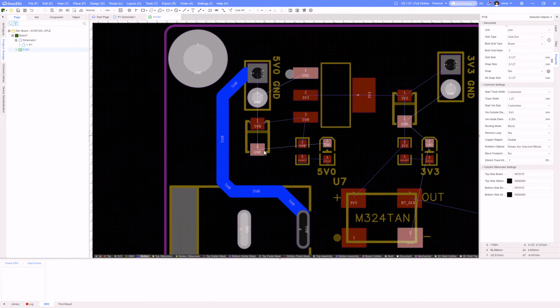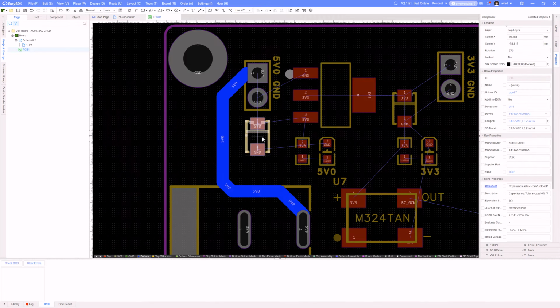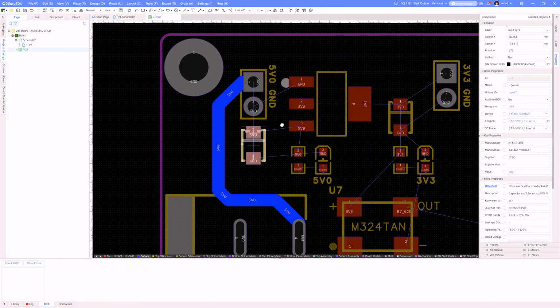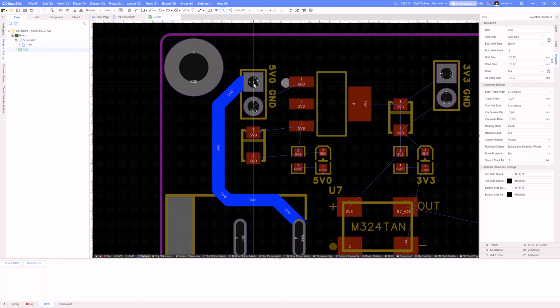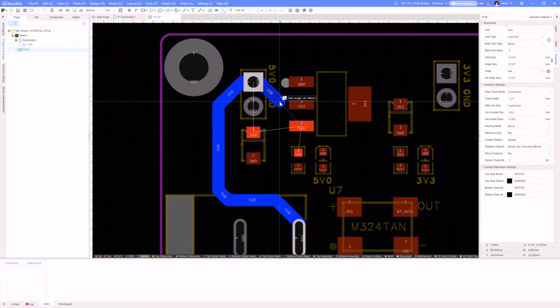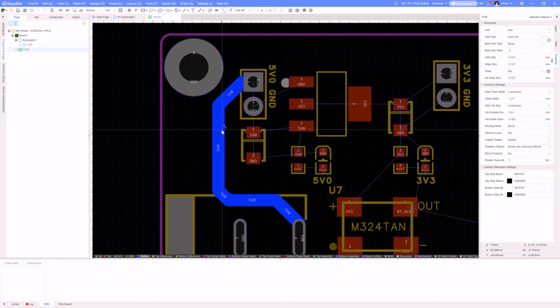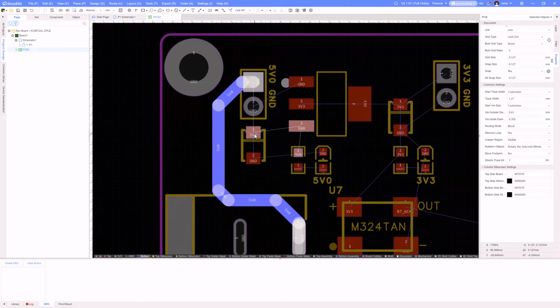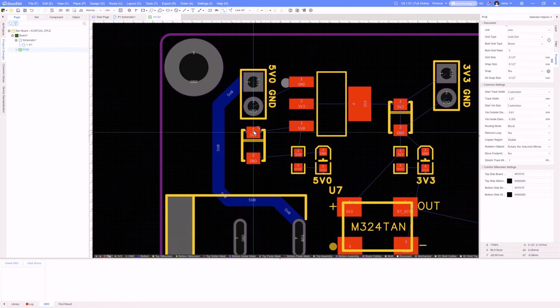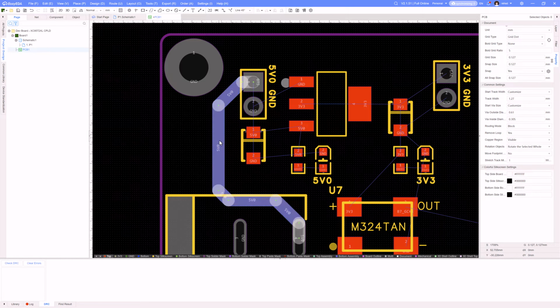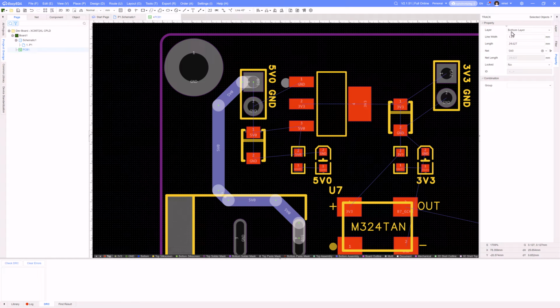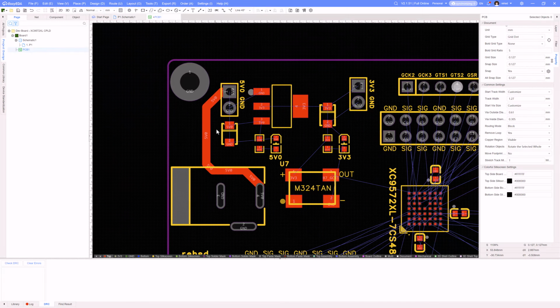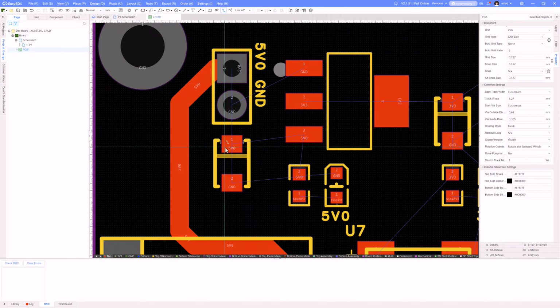Now I want to connect maybe this here. Again, if I click on this, this is a capacitor, so a 5-volt decoupling capacitor. So again, I can do my wire. I might say, well, that was too big of a wire. Or I can just say connect in from over here to over to the left. Now I notice it's blue, which means I accidentally put it on the bottom layer. I meant to do that on the top layer, so I'm just going to change it to top layer. And I want to take this 5-volt and just connect it in over there.